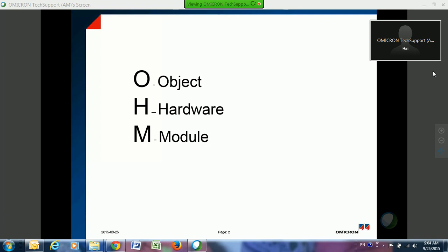But also in the object file, you'll set up some global settings, such as whether it's 2-phase or 3-phase. Typically, we're working with a 3-phase system, but sometimes you may get into a railroad that may use a 2-phase system. You can also put in the frequency, and information such as primary values and secondary values for your CT and PT ratios. That's one thing we'll be visiting during the initial part of the Quick CMC.